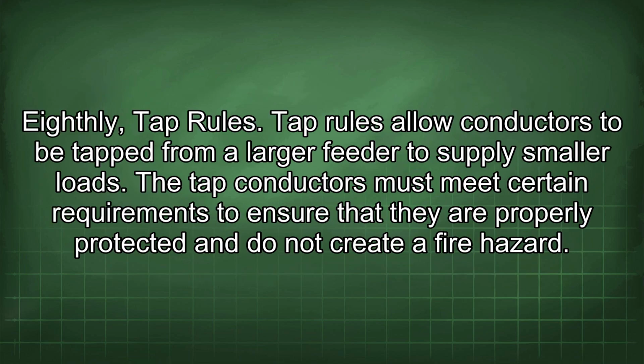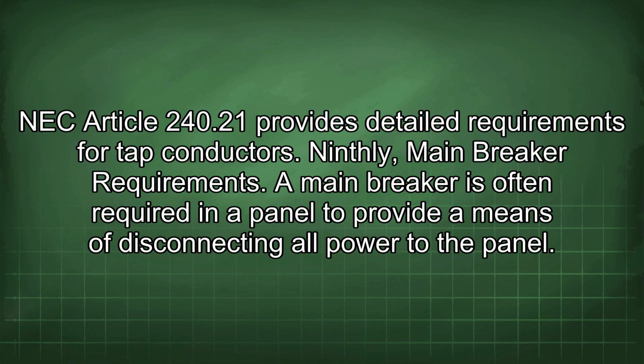Eighthly, tap rules. Tap rules allow conductors to be tapped from a larger feeder to supply smaller loads. The tap conductors must meet certain requirements to ensure that they are properly protected and do not create a fire hazard. NEC Article 240.21 provides detailed requirements for tap conductors.